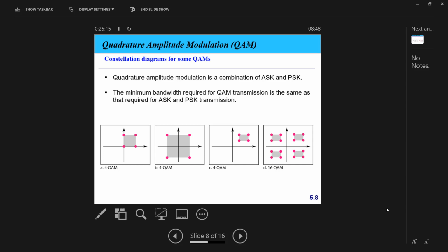And if we increase the distance between the symbols on the constellation diagram, it means better bit error rates, because I increase the distance so I can decode it correctly. But on the opposite, I will increase the bandwidth. Here r is equal to 4, so I'm sending 4 bits at the same time. Here I'm sending 2 bits at this point of view. Send 4 bits at the same time. Okay?